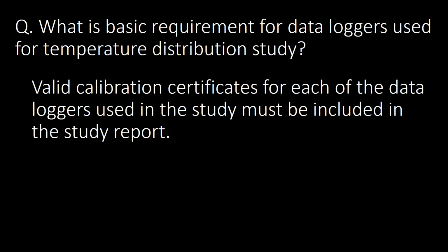What is the basic requirement for data loggers used for temperature distribution study? The very basic requirement for data loggers is the availability of calibration certificates. Valid calibration certificates for each of the data loggers should be available and shall be attached with the study report.